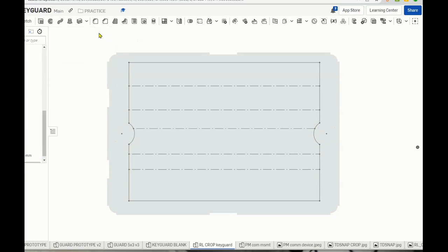And check on that. Then we're going to add another one that is the button space, and I'll call it row or something like that. So this is going to be our rows, and they're going to be 25 millimeters each. Using variables is going to let us manipulate things a little easier. We'll move those up in just a moment. The other one we're going to use is the space from left to right. So let's call that vert space, for vertical space, and it's 26.25 per our calculations in our paperwork. Okay.